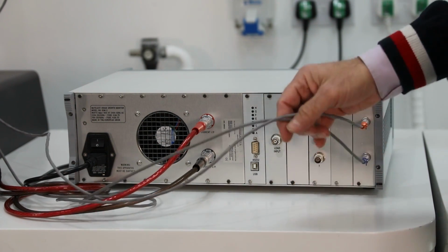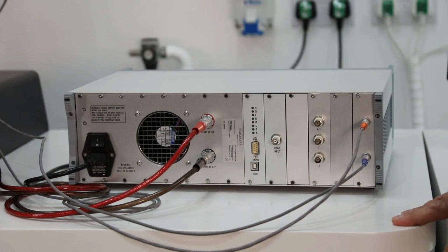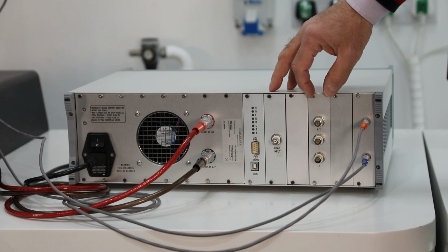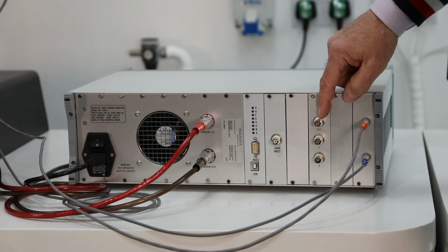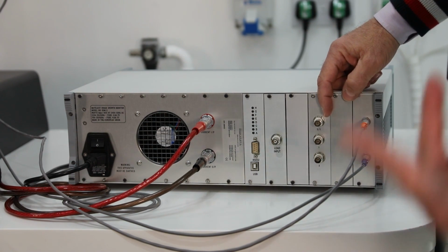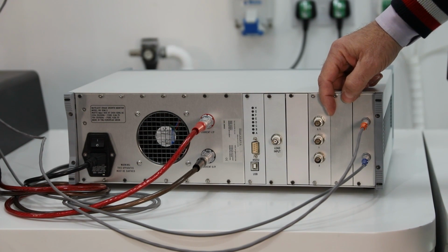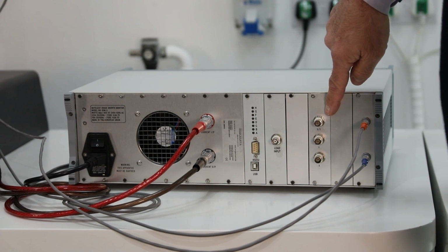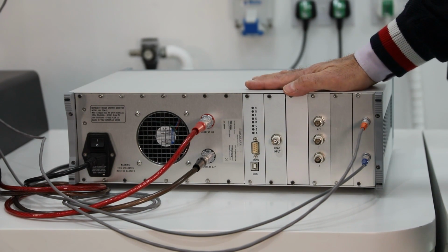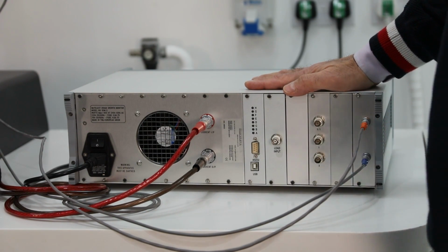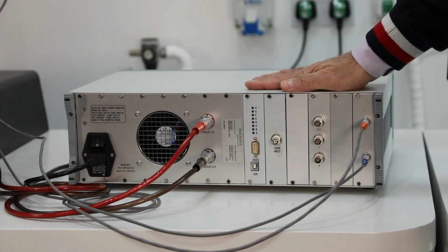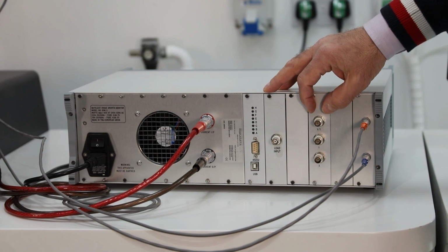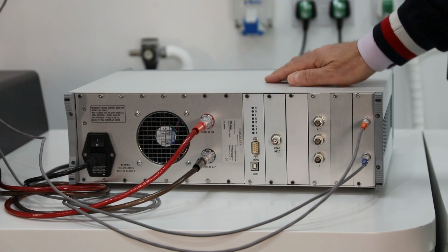And then you'll see a number of bays which are occupied with different electronics. That's an output. That's where effectively the analog signals come out of the instrument and go into the Instron test controller. We've got a 2-channel instrument, so we've got X, Y, and active reference, if you like, and then a division of that, X over Y, because some equations prefer that X over Y as the input.